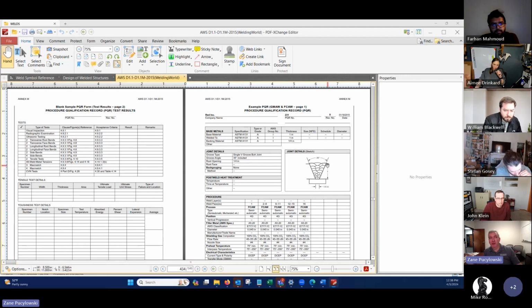See how it's multi-pass? The first pass is going to be flux core and a 4G with this filler and these temperatures. 2 through 8 is going to be this. This is a 16-pass weld. That's probably what they're going to have to do for those 4 plates for contract fab foreign, and why I was trying to get it down to a 1-pass weld. At 1.5 inches, they'd have to do something similar to this, right?